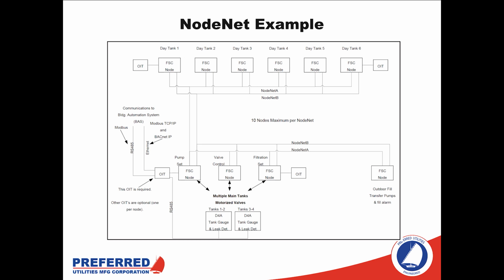Now, one of the other advantages of this is that since it's operating over a hardened, redundant communication network, all of the wiring for a large system such as this is greatly reduced while increasing redundancy. So we don't need a pair of copper for every level point, for every leak detector. We have our communication lines that can be run and save on all of that infrastructure.